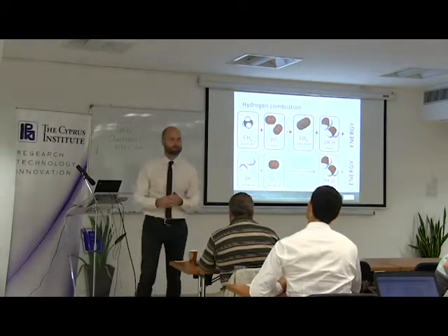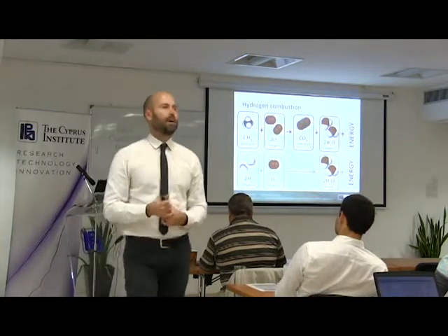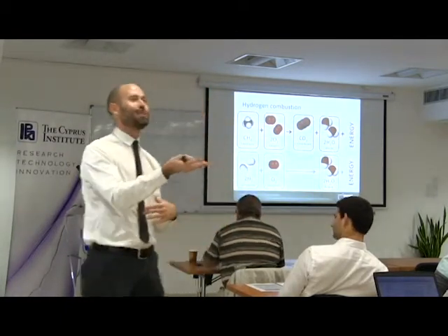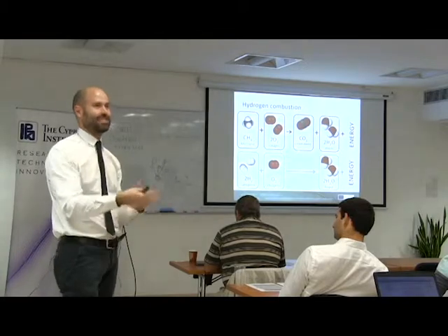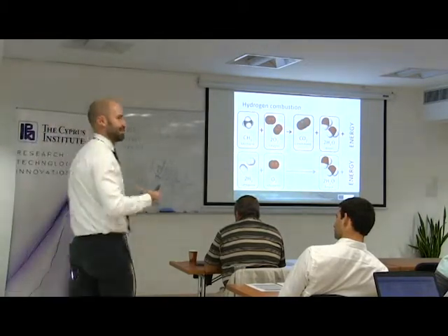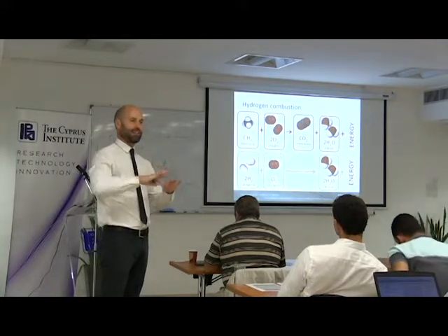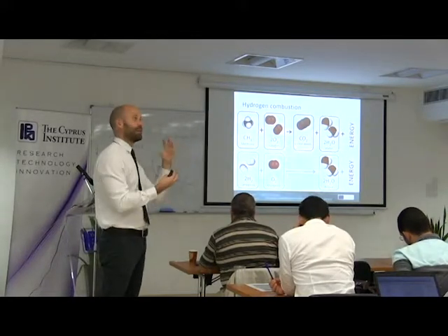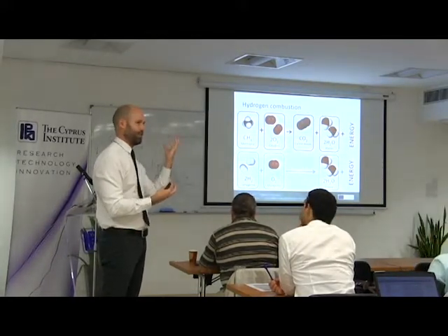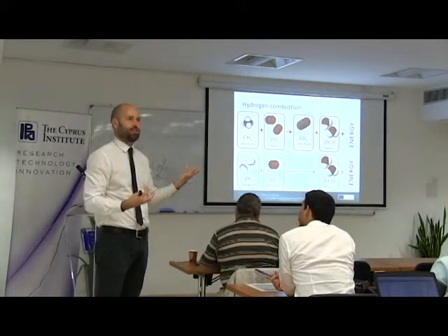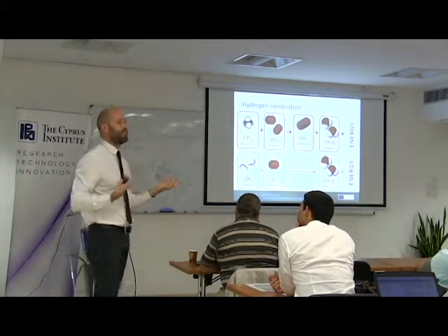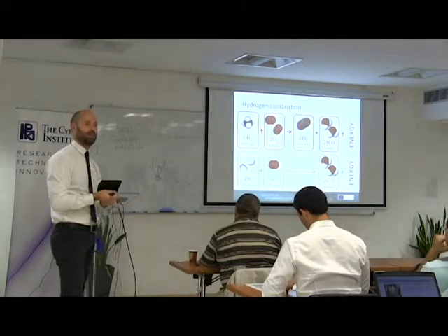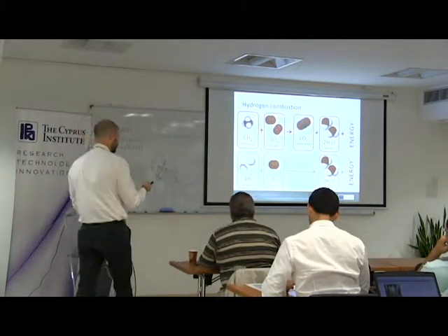It's not mandatory to use solar energy to crack methane. You can do it also with fossil energy, but of course the interesting point is providing clean heat, solar heat, to do this type of process. In any case, cracking is a different class of processes, but the idea is the same. You take the fossil fuel, or not only the fossil fuel, the carbonaceous fuel, because we will see you can also have biomethane, for instance, produced by anaerobic digestion, and you take away the carbonic part, either as CO2 in the reforming, or as solid carbon in the cracking.